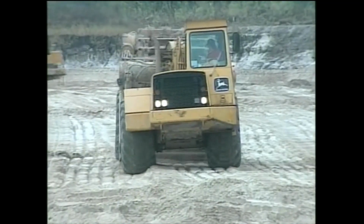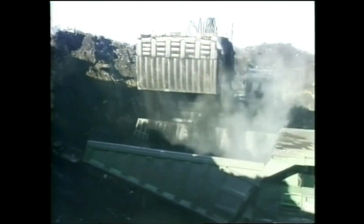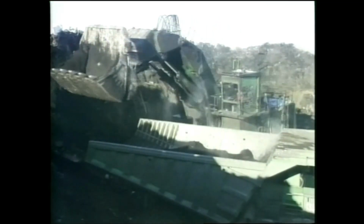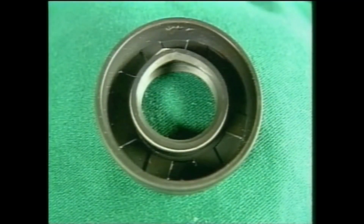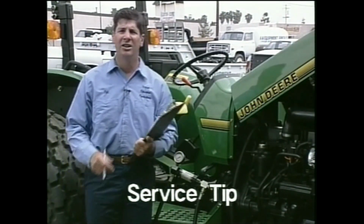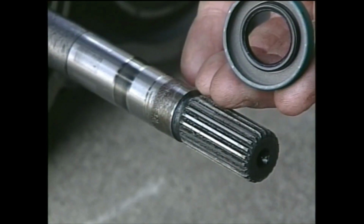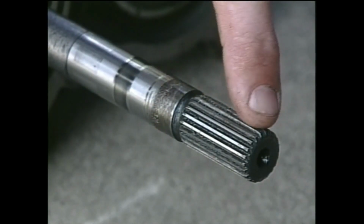Generally speaking, the higher the pressure and flow rates of a system, the larger the quantity of heat generated. Excessive heat oxidizes the oil and accelerates the hardening of the seals. As seals harden, they lose their elasticity and ability to seal on the shaft. Hydraulic oil runs hotter when the oil in the reservoir is low. Low oil levels have less surface contact with the reservoir to radiate the heat. If the system you're working on shows signs of overheating, look to see if there might be an oil cooler that needs cleaning. Many pump seal failures also result from improper installation.